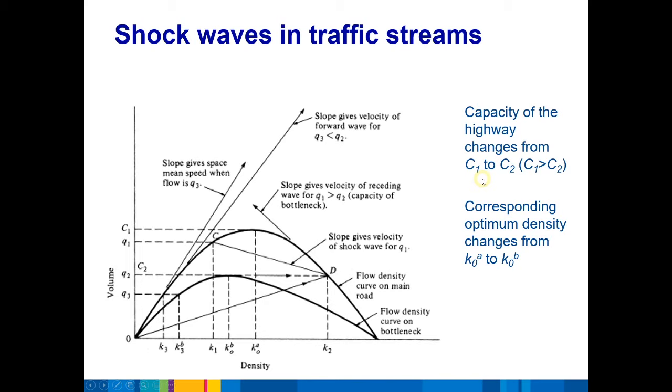So let's say all the vehicles are traveling in the north direction. We've got a 4-lane highway. Suddenly we have a breakdown or a truck rollover or some horrible thing, and we're down to 3 lanes. Now all the vehicles are traveling north, but the shock wave actually moves south. The shock wave will travel backwards in the space relationship. It will increase the density of flow. It will decrease the speed. It will decrease the flow rate as we follow this shock wave back up the traffic flow.